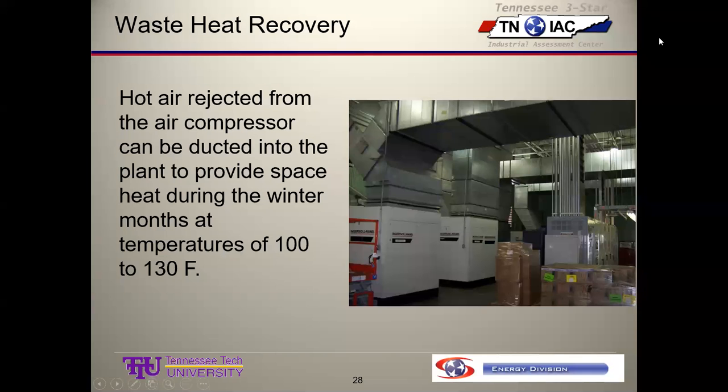Okay, this slide shows the ability to recover and use some of this waste heat. These are those Ingersoll Rand, I think they were 400 horsepower compressors, so a pretty good size compressor. And they're air cooled. And so what they do is they just suck air in intakes from the compressor room. And then they blow it. There's probably a 4 or 5 horsepower, maybe a little bit bigger fan in here that blows that air across a heat exchanger that cools the compressed air down.